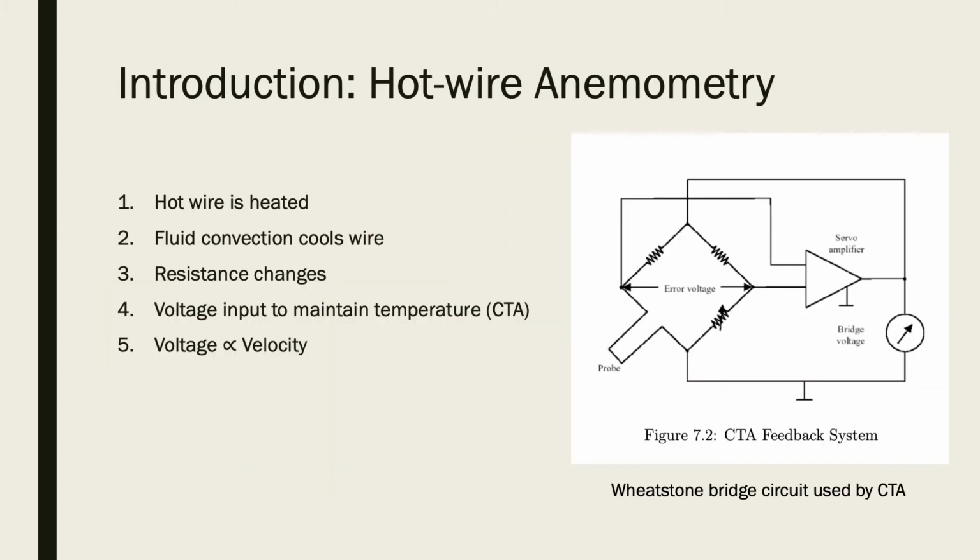Hot wire anemometry is used to find flow velocity quickly and precisely. Although anemometers can be fragile and intrusive in wind tunnels, they sample continuously, have small spatial averaging, and they have a fast frequency response. Also, the strong signal to noise ratio produces good velocity measurements and tracks small changes effectively.